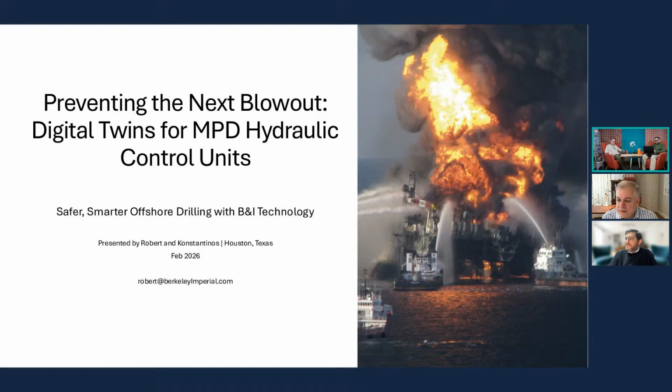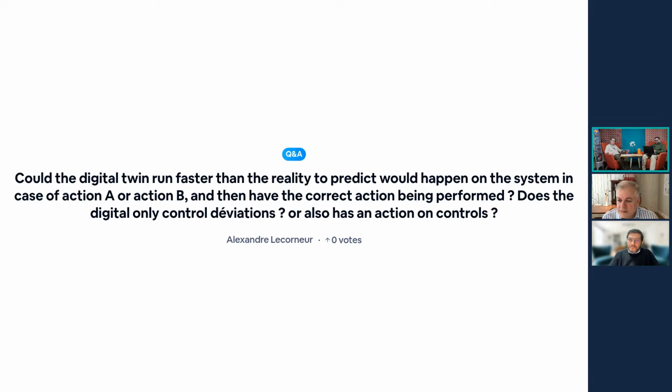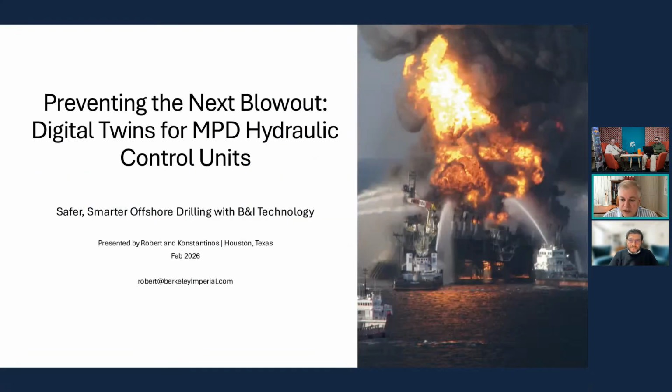Alexandra has a good question here too: whether you can run it faster than real time and use it to predict and make proper choices, almost like model predictive control. Would that be possible? It depends on how complicated the hydraulic system is, and we are currently investigating that. We would like to be able to do model predictive control. My gut feel is that for simple hydraulic systems that might be possible, but for the more complex ones, what we're observing with execution speeds is we may struggle to do that.